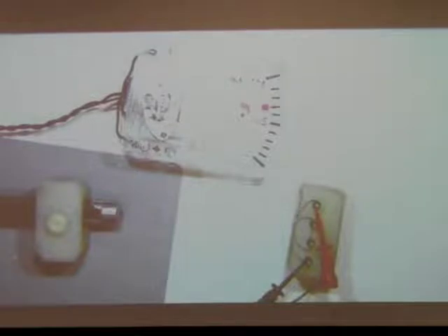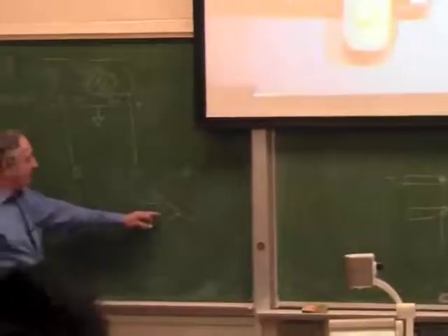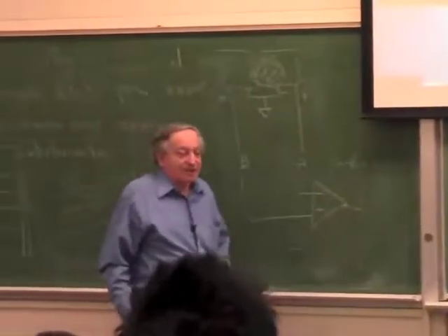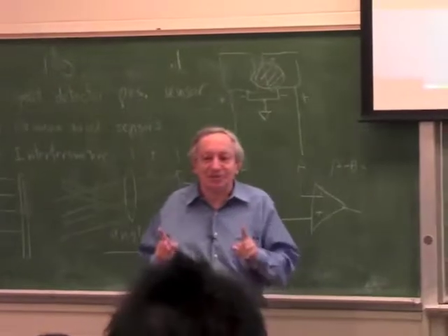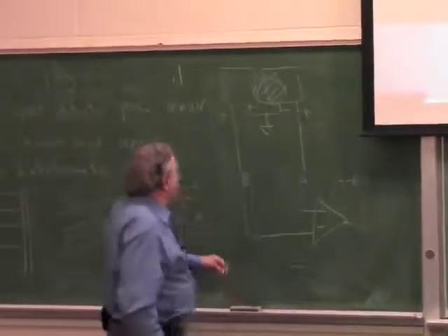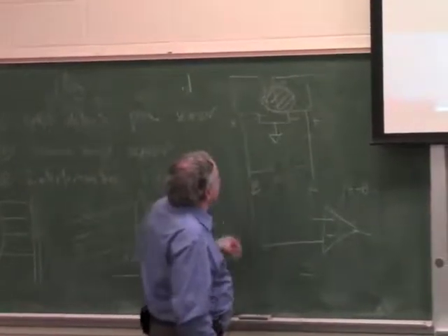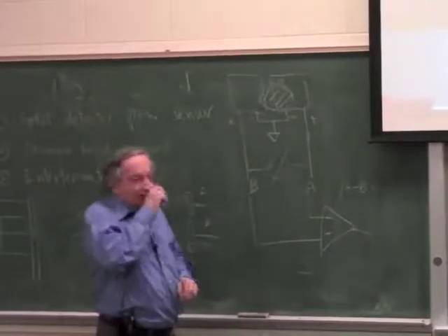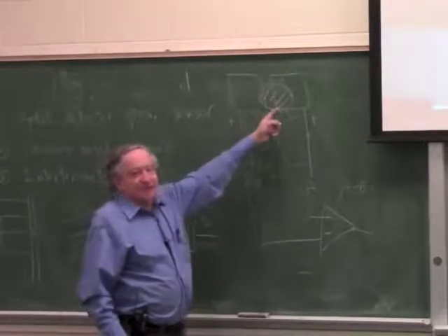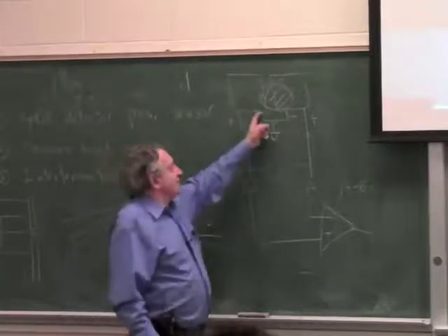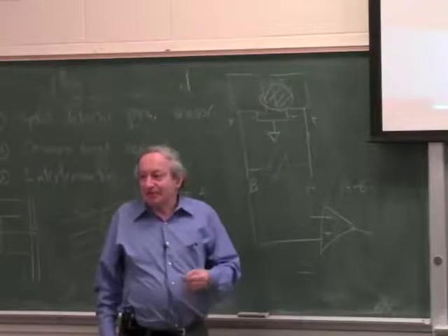Okay, so this is a split detector, a position detector, which can be made incredibly sensitive, because you can imagine if you have a laser pointer which is very bright, and you are amplifying it here by a lot. And interestingly, what I'm showing you is without any amplifier. In this demo, I just take A and B directly and put a meter between them. So without any amplifier, if I have a bright source which hits the detectors, these detectors will create a couple of milliamps each.